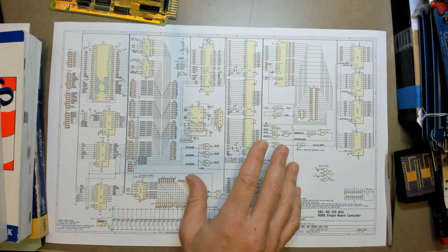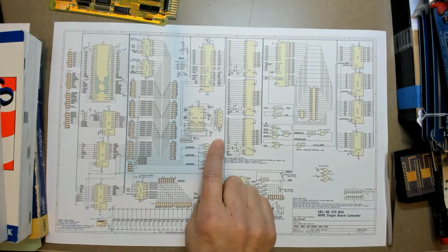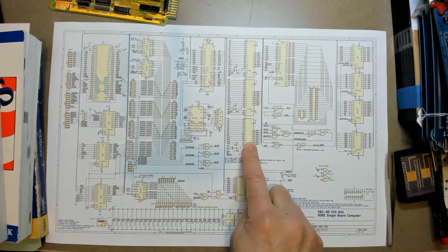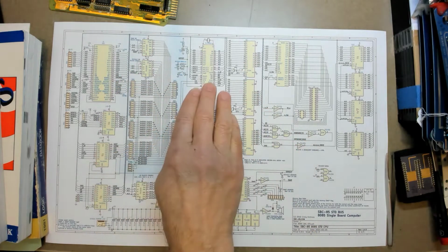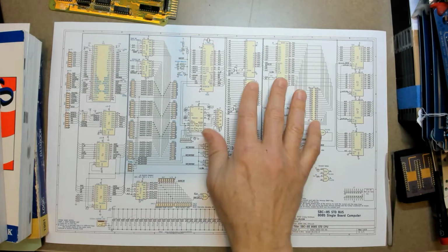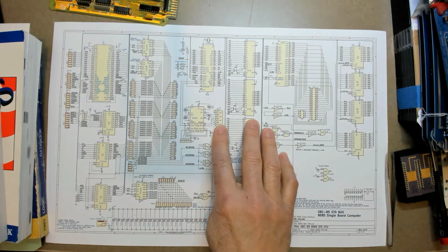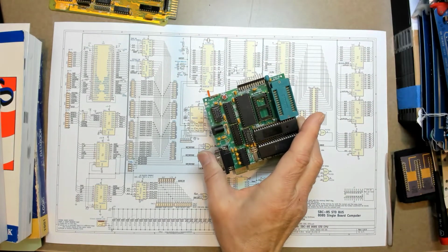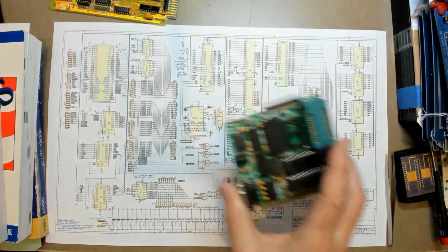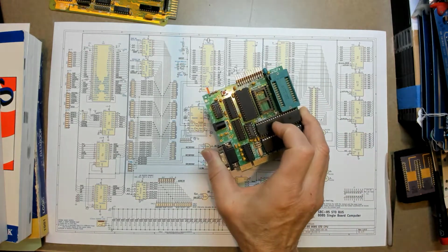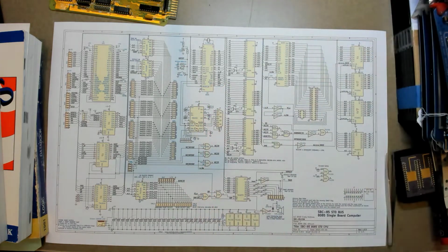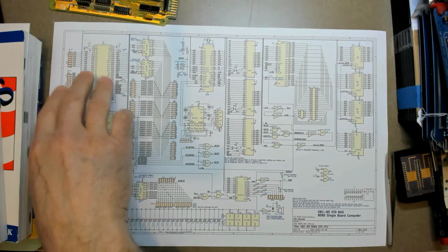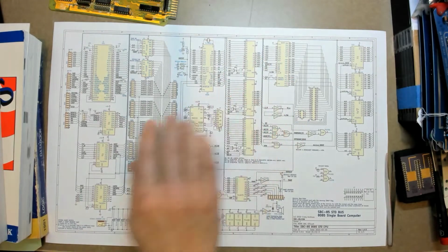As I mentioned in the first video on this board, the core components of this processor board are the memory decoder, the processor, and the 8155, and that's all fairly generic. It was from a project that I started, the SBC85 single board computer. I did this a few years ago, and basically the core of this board is the same as the core of this SBC85 board. So we've taken that core and shrunk it down, and then on each side we have the specific additions to make this core design STD Bus compliant.